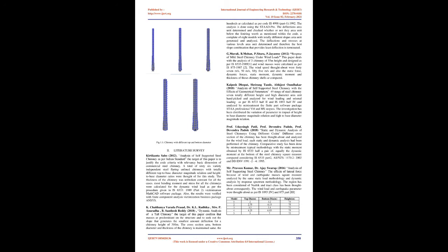The geometry of a self-supporting steel chimney plays an important role in its structural behavior under dynamic lateral loading. This is because the geometry is mainly responsible for the stiffness of the chimney. Some basic geometrical parameters of the steel chimney, e.g. total height, diameter at the exit, etc., are associated with the corresponding environmental conditions. In addition to that, design code IS 6533, 1989, Part 2 imposes several criteria on the geometry of steel chimneys to ensure a desired failure mode.